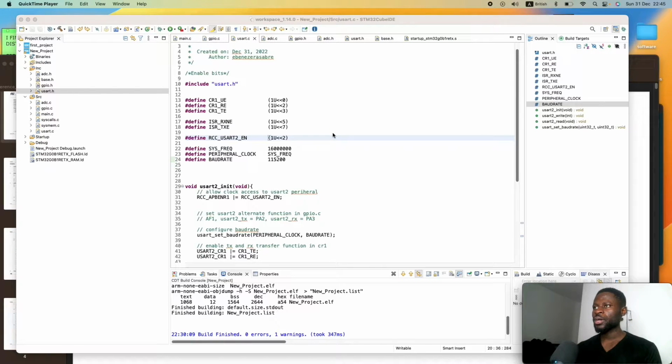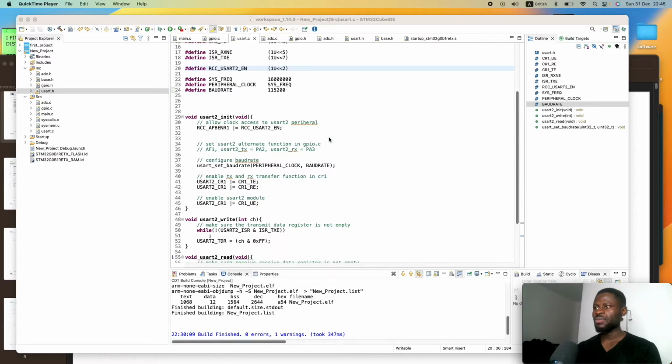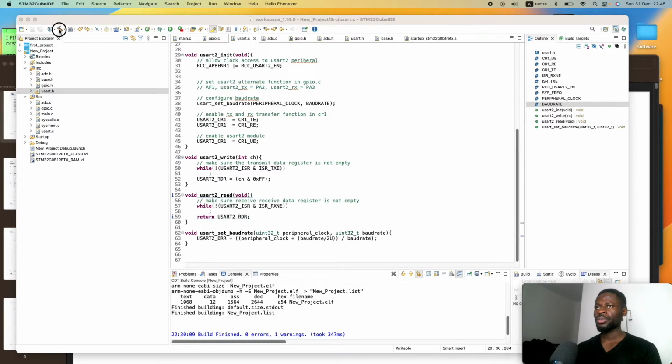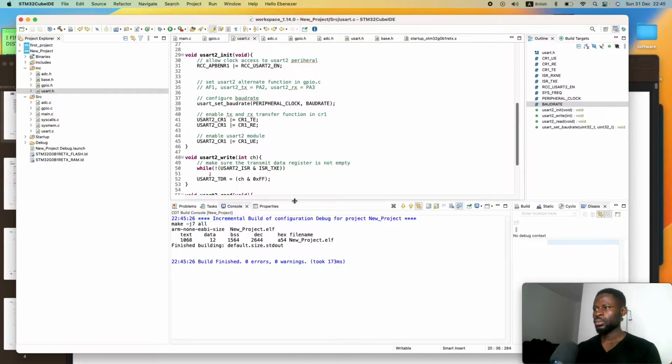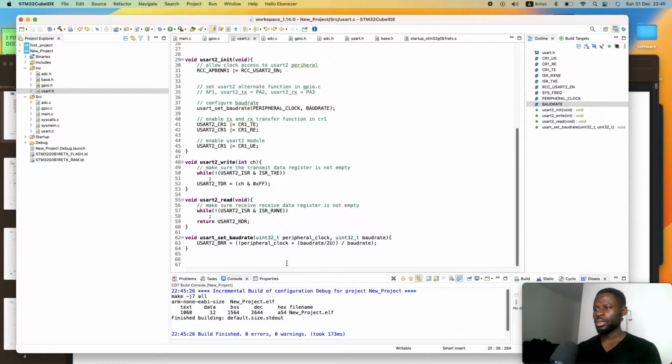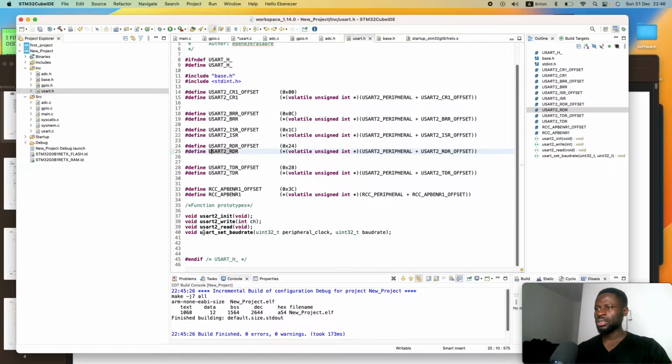Hello, before we go ahead and write the ADC header file and source file, let us run our program. Okay, it looks like the program is compiling, but there is a mistake here. We are reading something, right? And we want to return at least a character. That is a bad mistake. So make sure you correct this and go to the UART header file and also change the return of the read. Okay, make it a character.